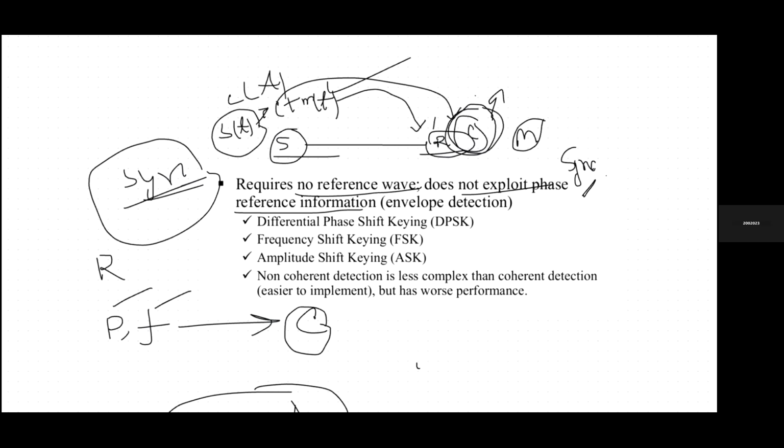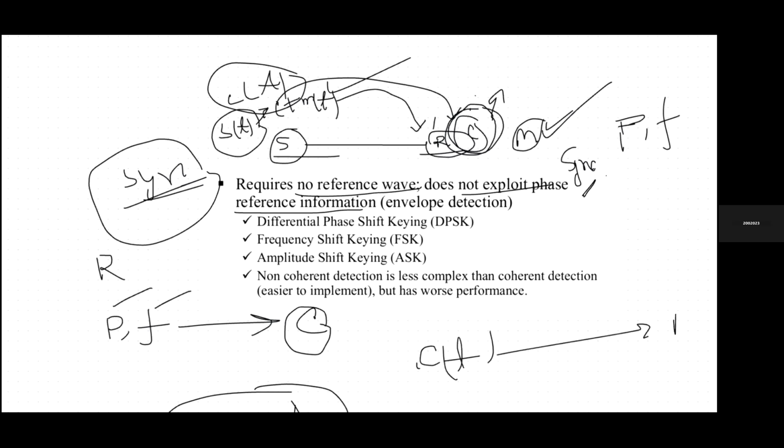We will compare what? We will compare the phase or frequency of the main transmitted carrier signal with this signal. After matching these two, we will extract the message signal only from the modulated transmitted signal. That's why this is called the synchronization process. We will synchronize here the sent carrier signal with the receiver end reference signal.